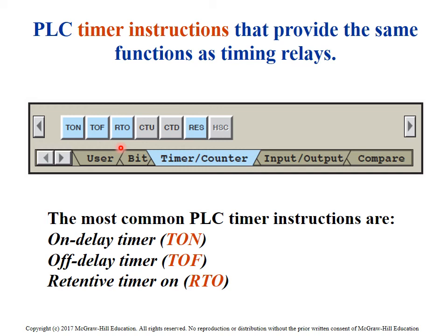It's identical. So timer on, TON is timer on, TOF is timer off, and RTO is retentive timer on, which requires a reset, an external reset, and we'll be getting into that shortly.